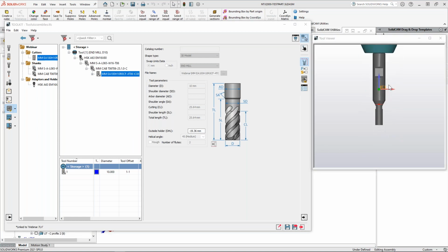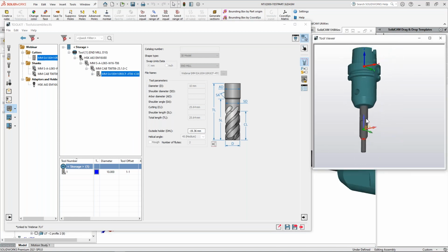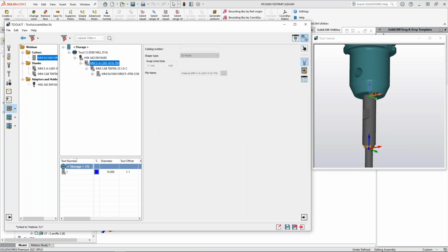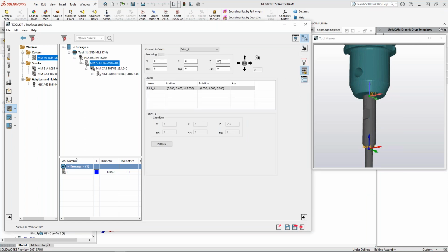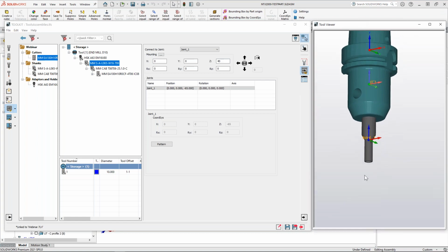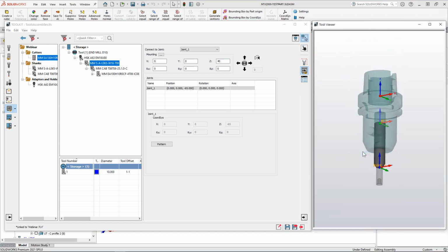Here you go. Now there's a couple of things that we need to do. As you remember, we just put all the coordinates there, and I put it for a good reason. If I click it over here, now I have a connection and manipulation to say where my element will be. And a very nice tip for you: you can also do a right click and make a focus, which will basically focus and highlight only the element that you are actually modifying.